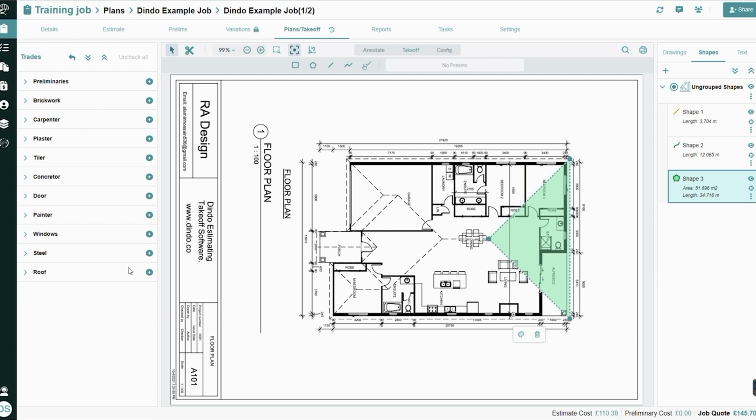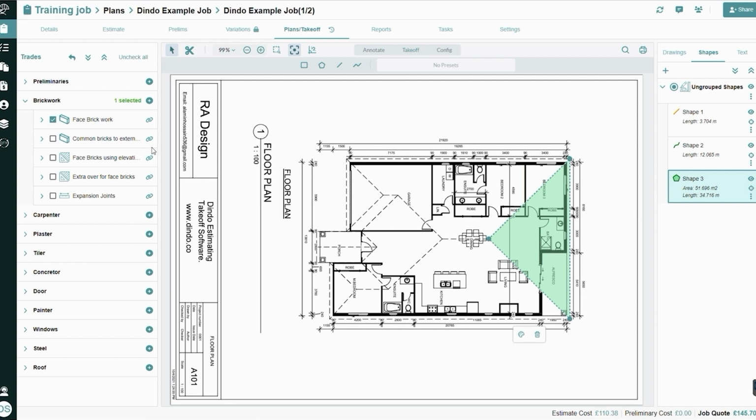So that is a roof area by pitch. Now we'll look at a vertical area, something again just different. We'll go for brickwork, the outside face. Again, we'll pick our drawings. We'll go for yellow. We might hide everything out of the way by hitting this little eyeball. We haven't really looked at shapes, but we'll just hide everything with the little eyeball.